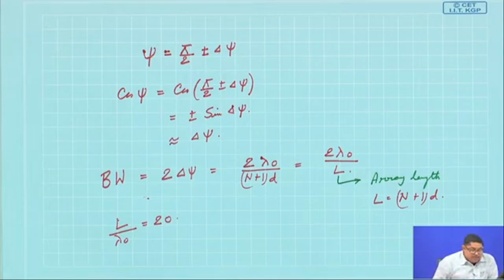So, that is why array antennas for broadcasting are not so popular. You see, this is a 1 megahertz broadcasting thing. So, broadcasting people generally take only a single antenna, dipole or monopole basically, with a huge tower. For normal communication it is impractical, but for weather radar or research systems for extraterrestrial observations, looking at distant stars, this type of arrays are made.